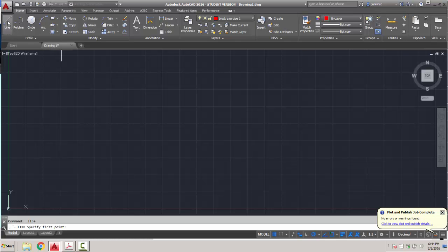So now we're going to go to our line tool, and we're going to just start anywhere. We'll just create a line 8 inches across. Whoops, didn't mean to do that, sorry. 8 inches. Come down a distance of 12. And get an angle there. It doesn't really show what it is, so I'm just going to right click, and I'm going to draw a line straight down the middle, starting right here. 12 plus 2.5 is 14.5. And then we can grab this, connect it.